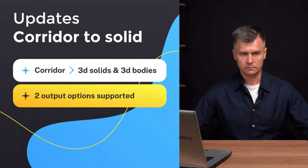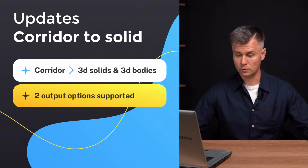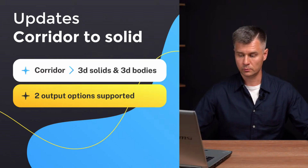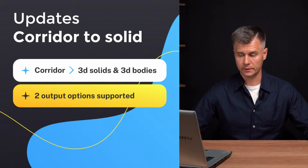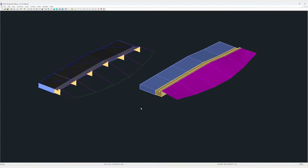Next item is that the export supports two output options. First, when the created bodies or solids are added in the DWG database, current database or another database with specified settings, and corridor related data in property sets. Second option is when raw geometry in terms of OD, the OD model geometry pointer, is created. So we have also a video to illustrate these two export options.